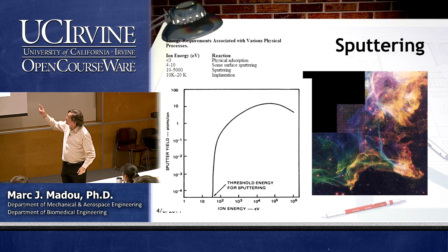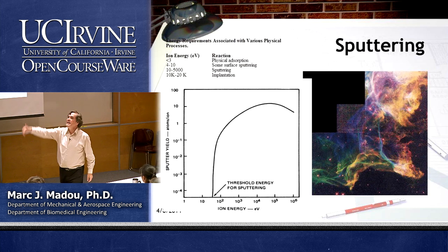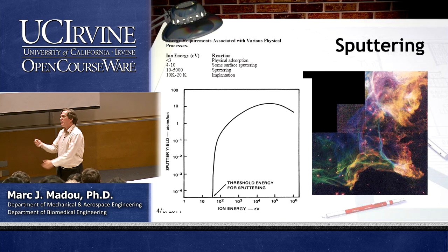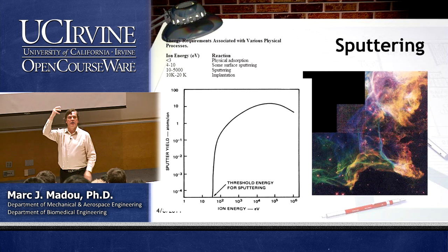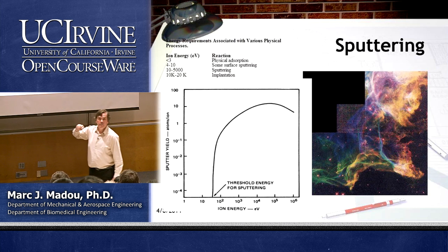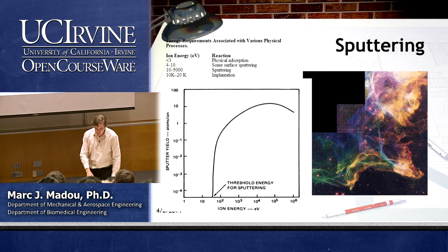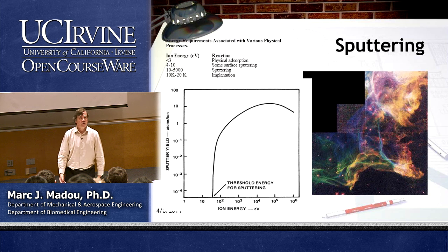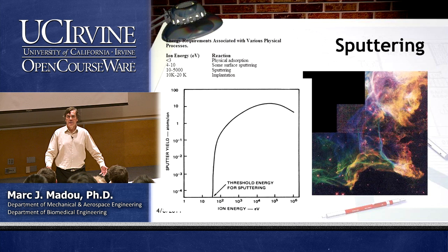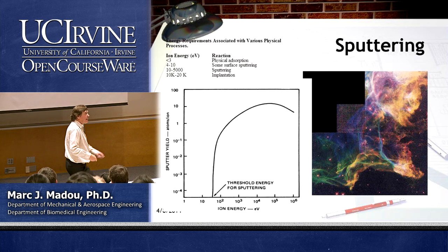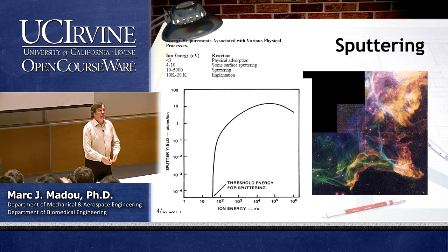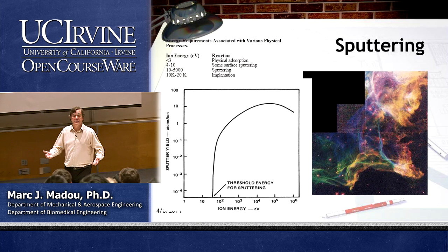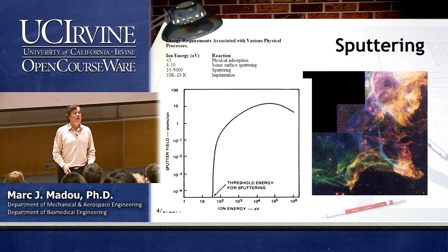That's it. Next one, ions for cleaning surfaces. If you have carbon or oxygen contamination, you come in with the argon ions and they clean it off. Third one, very important. I'm going to sputter off top layers of gold, platinum, any material. Billiard-wise, mechanically, I'm kicking the atoms off. And I kick off at a certain rate, 5 layers, 10 layers, 20 layers. I dig into the material, I etch it.